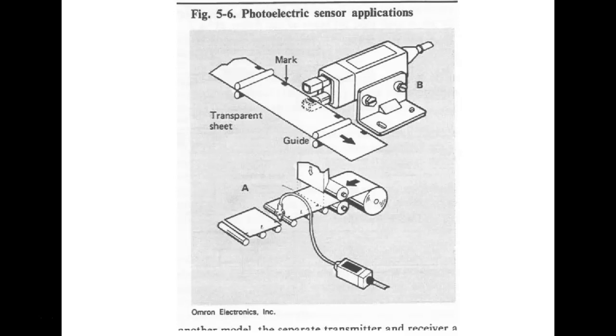Every time we have a photoelectric sensor, the problem is dirt. It's dirt. If you're in an environment, unless you work at a semiconductor manufacturer, where they limit how many particles they can have per million cubic feet of air, almost all plants will have some type of dust, right?